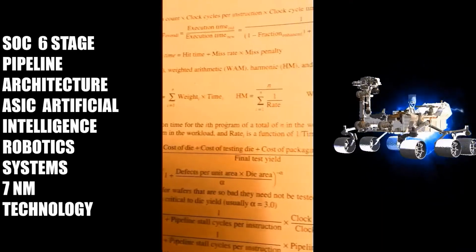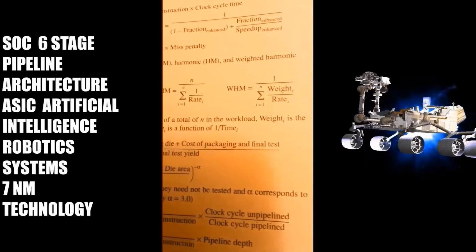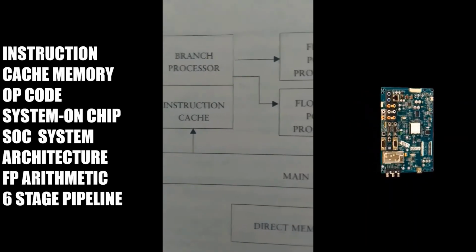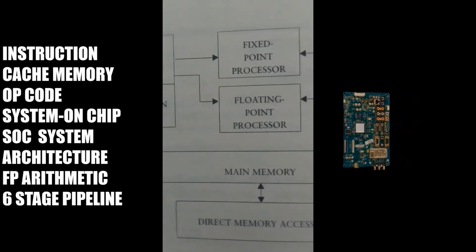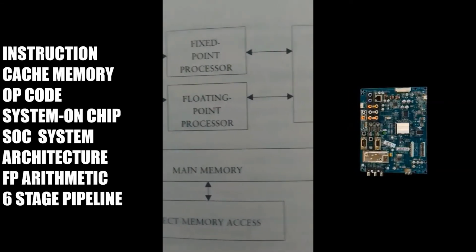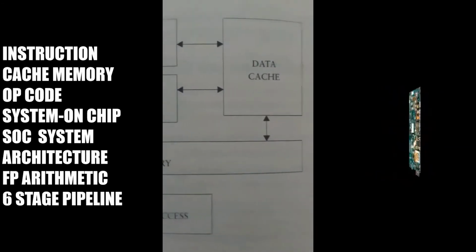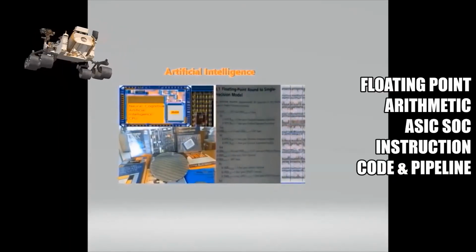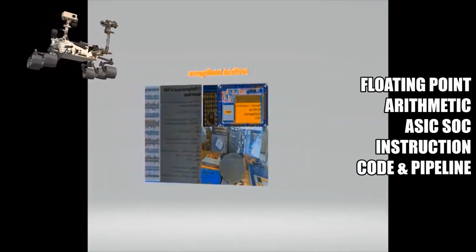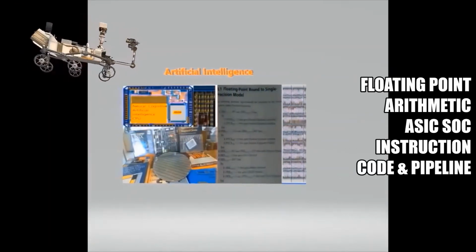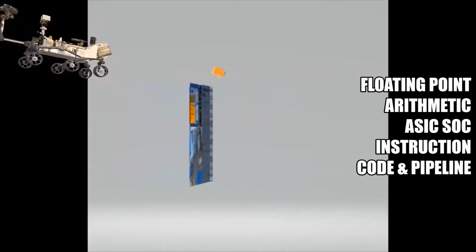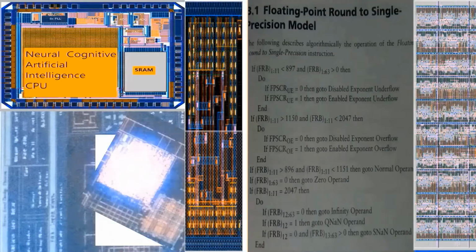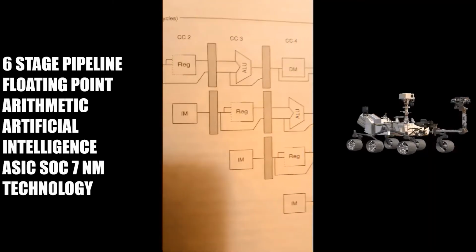The floating point pipeline consists of 3 functional units: a floating point divider, a floating point multiplier, and a floating point adder. The adder logic is used in the final step of multiply or divide. Double precision floating point operations can take from 2 cycles up to 112 cycles for a square root. In addition, the various units have different initiation rates.